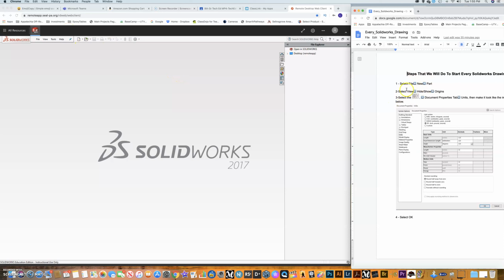So anyway, this is how we start every SolidWorks drawing. Now, one of the things I told you in my last video was that I wanted you to go up here. Notice how we just have icons, and when I roll over SolidWorks, I just have words. We want both of those to show. So if we roll up here and hit the thumbtack, now they're both there.